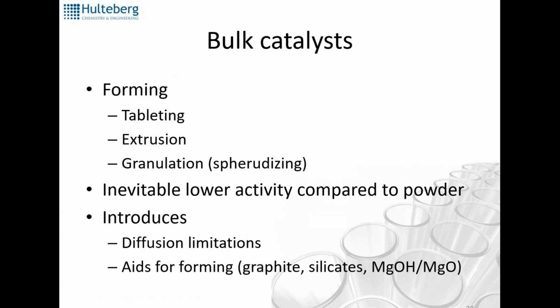Tableting is a very good way of achieving hard, well densified powders or tablets, and you can use them where a large amount of mass is important in the reactor. So for any equilibrium reaction like the water gas shift or the ammonia or methanol synthesis, tablets are great because you get a lot of mass into the reactor. It's basically limited by the actual reaction on the surface and not transport limited.